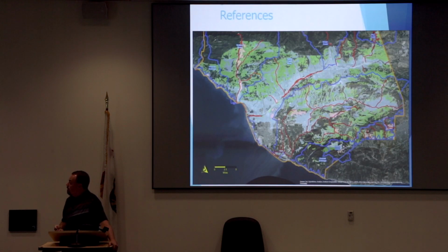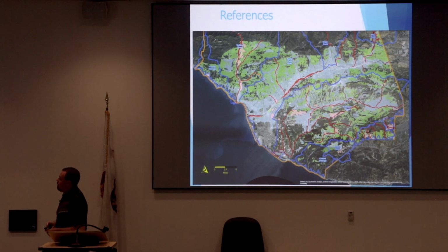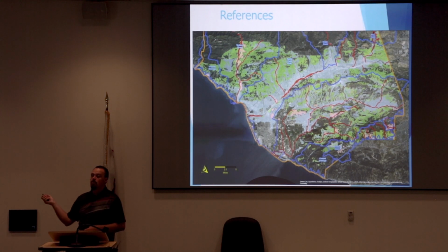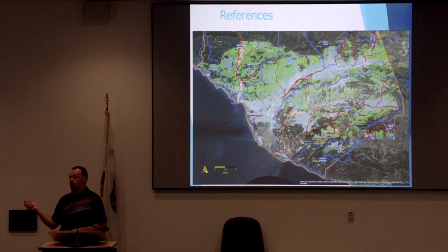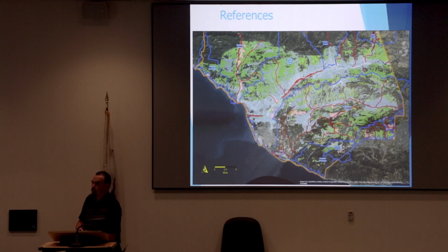And this is an example of those soil files that I've got in my MXD. Here I've just got the different watersheds shown: Ventura River, Santa Clara River, Calleguas Creek, Malibu Creek, and then some of the coastal drainages. Now in this, I've removed soil number 1 and 2, which is supposed to be poor for infiltration. The green soils are soil number 3, which are borderline for infiltration. And soil number 4 through 7 I lumped in as the blue. So you can see where the really good infiltration areas are supposed to be.